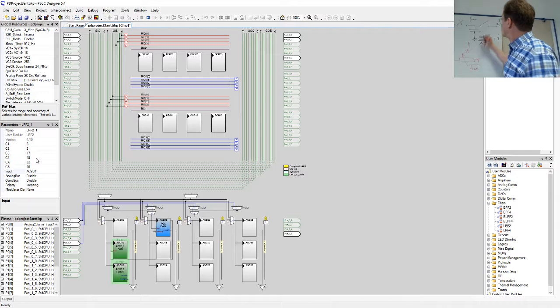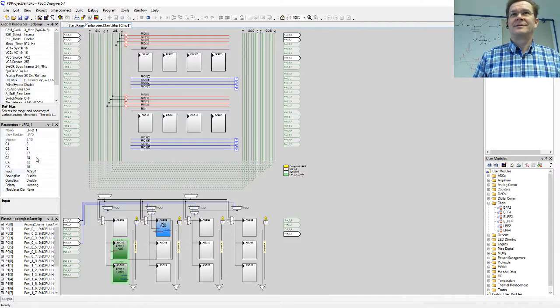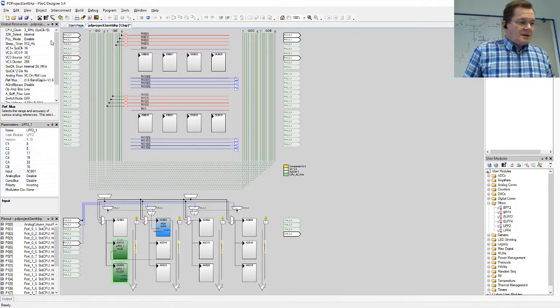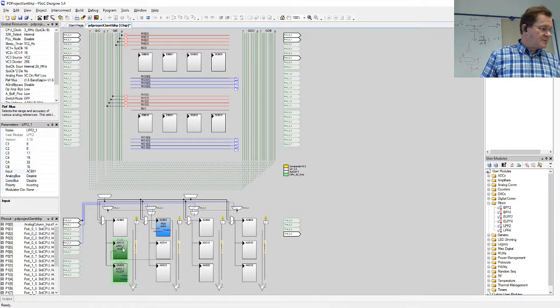So now we just need to find a way to produce 400 hertz signal from 24 megahertz. So we need some dividers. This 480 would be better value, right? Since then, 24 megahertz divided by 480. It doesn't make any difference.